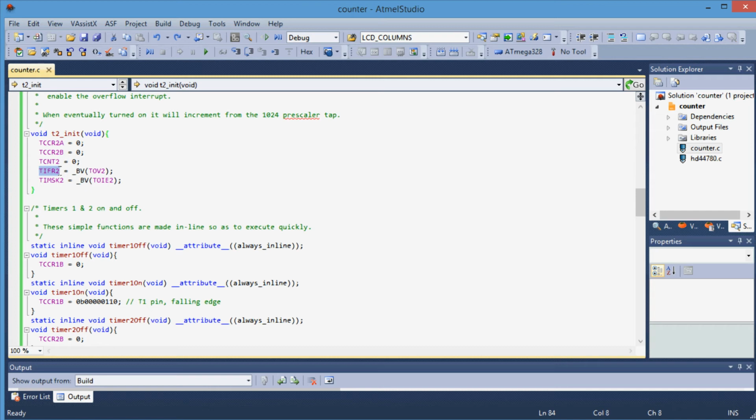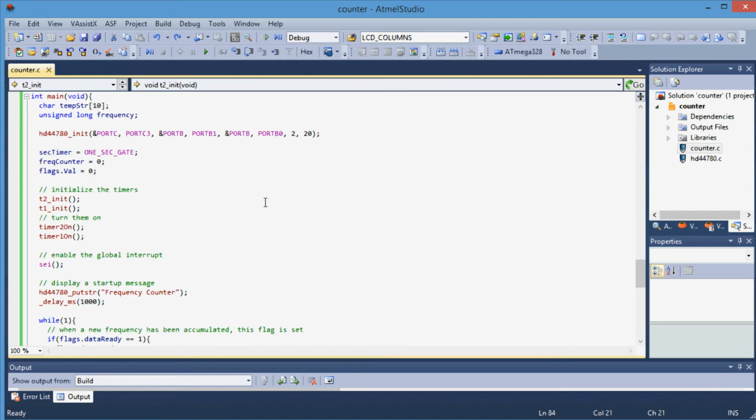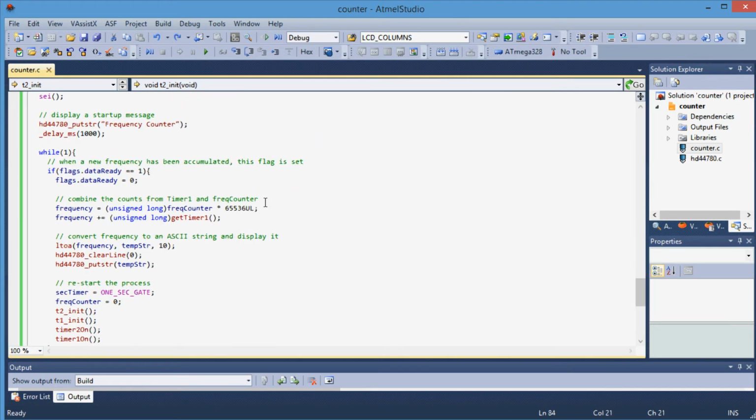But in that case, when you're just looking at that flag and you're not using the interrupt service routines, you must manually clear it. You must have a piece of code that actually clears that bit. If you don't clear that bit, you will just run back into the interrupt service routine forever, or that bit will just remain set and your code will act kind of funny. So that was a quick aside here on automatically clearing the interrupt flags.